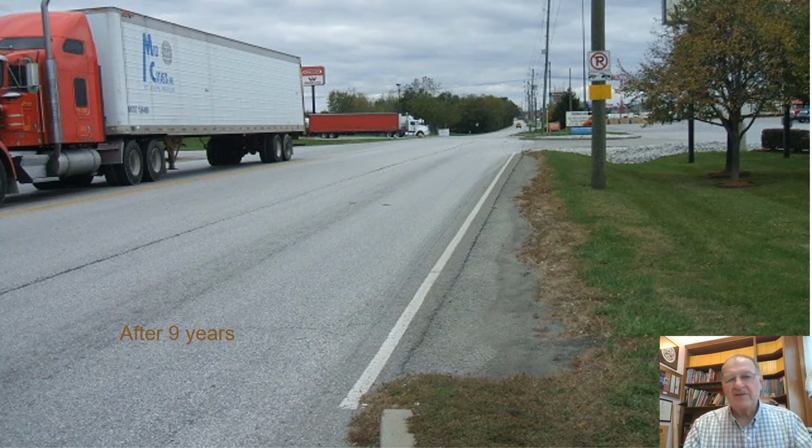Well, that residential mixture had about 35% natural sand in it. For a residential street that gets a garbage truck once a week, perhaps a school bus twice a day for a couple hundred days a year, the odd delivery truck, it works perfectly fine. But if we put it under 2,000 Class 8 trucks, 18-wheelers, traveling at about 10 to 15 miles an hour, it doesn't work very well. And that's what we found out.